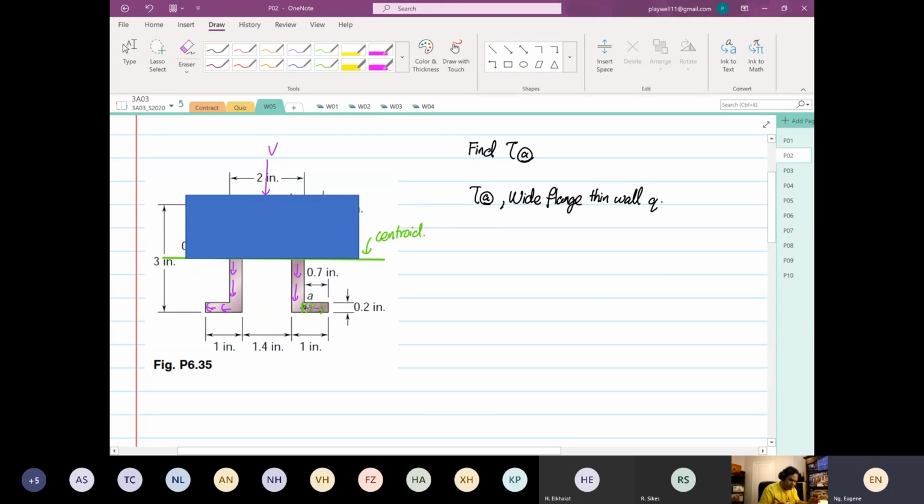You only consider one Q. Okay. So from here, by applying the rule that we have stated, the datum is from the centroid. The analysis will start where y is at the maximum. So that's why you only consider this area. Okay, and the end of the shear flow is over there. So you only need to consider one arrow, and only that area over there. You don't need to consider left and right.